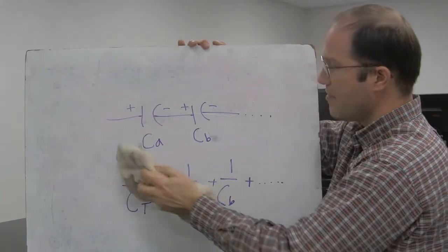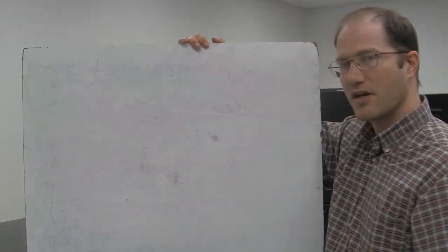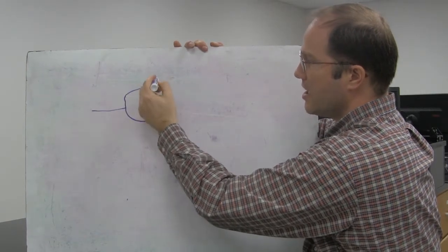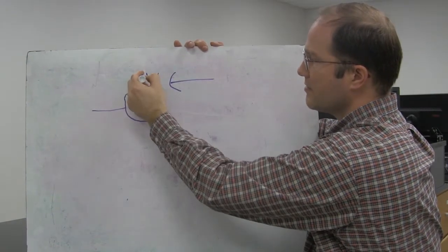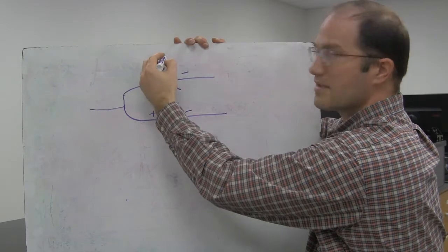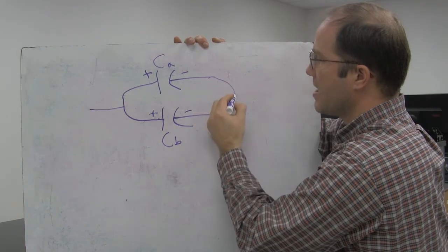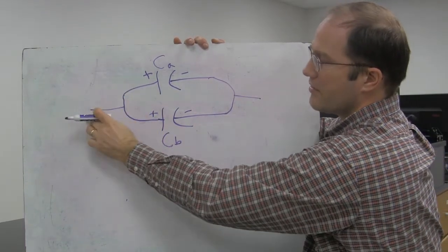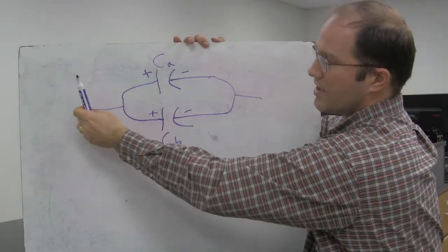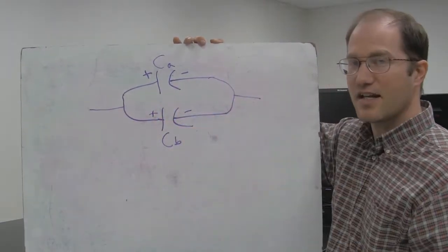Hopefully yes. There's another way that you can connect those capacitors together, and that is in parallel. And again, I won't go into the theory behind the equation. You'll do that in lecture. But if you have a parallel connection, and say you put one capacitor up here and another capacitor down there, we'll call this capacitor A, this is capacitor B, and the positive ends are connected together, the negative ends are connected together, but there's a choice. You can branch and go either way through a capacitor. So these are said to be in parallel instead of in series.